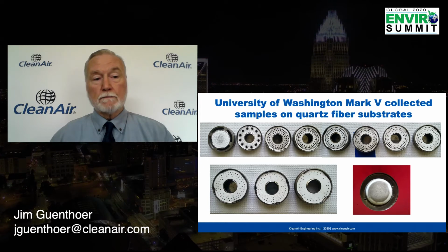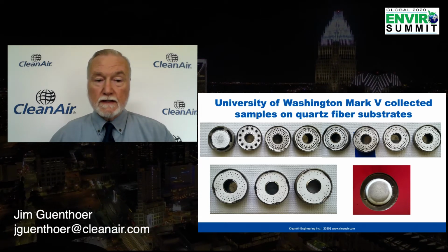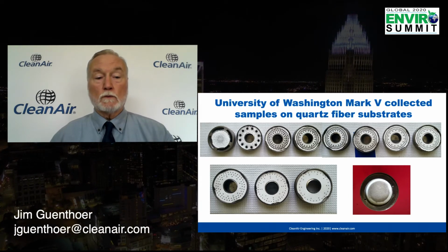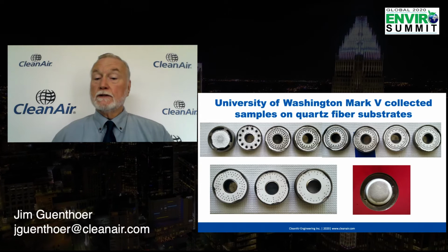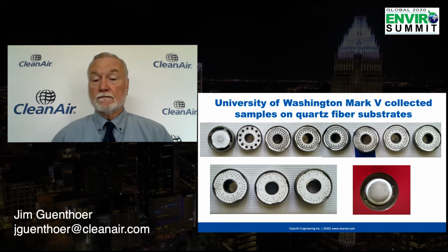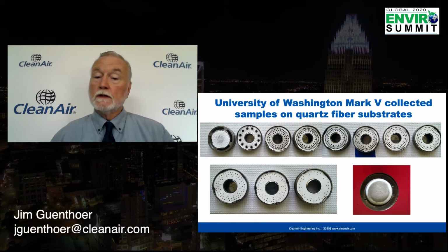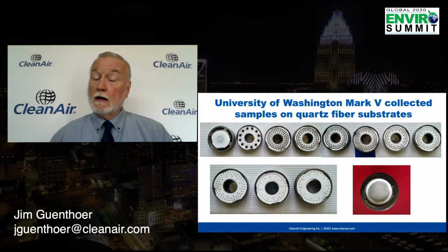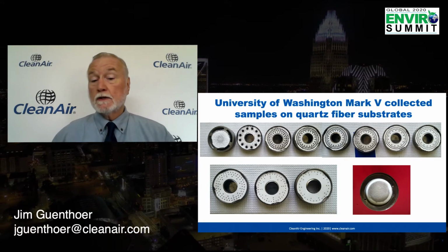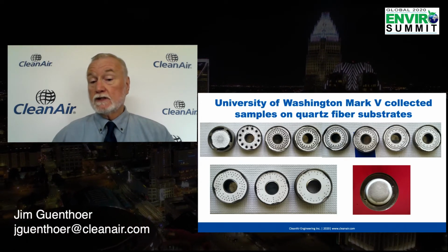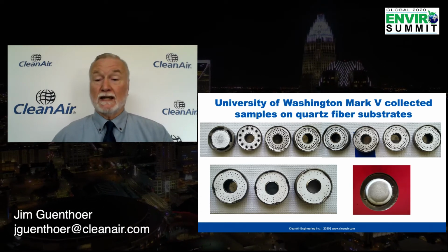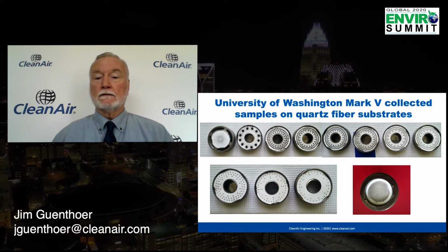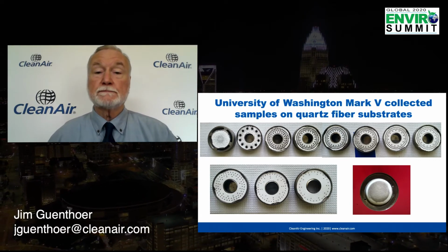So here we are. This is right behind where the pre-cutter is, and you can see the patterns of increasingly finer, smaller particulate working its way down through. And here's the backup filter, again, a 47 millimeter ultra pure quartz. You figure these particles that are here, the D50 of this stage is probably 0.2 microns. So whatever's gotten through, you notice it's like just a staining on the filter. So this is an ultrafine fume of particles that is being captured in this backup filter, to give you an idea how small this is.